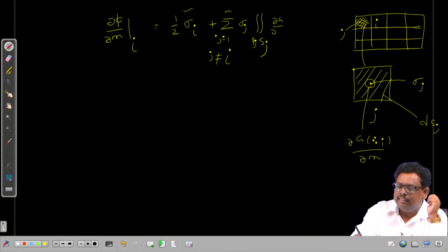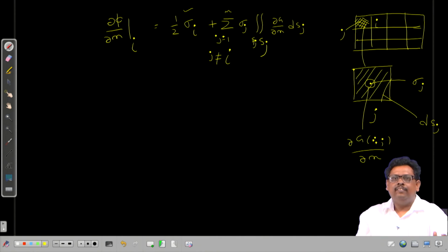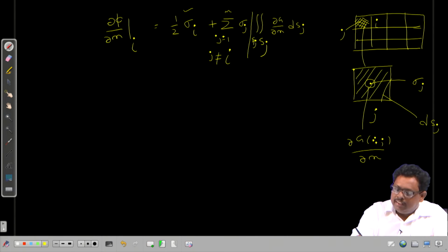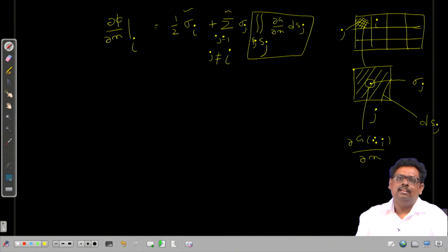Now, it is clear. The difference is that earlier I used the functional value multiplied by the area, but now we are performing the integration over this panel, and this would be the numerical integration. If it is a one point Gaussian quadrature rule, then it is similar to this. Otherwise it will be different.